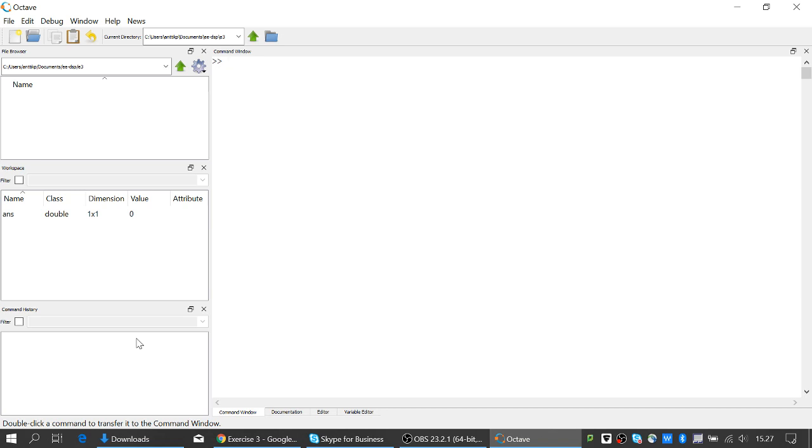So a stable system. And based on the theory I showed you earlier, the amplitude response should look more or less like, well, here we have Fs/2. We have the amplitude response going to 0 here, and we have a local maximum here. Maybe it looks something like that. I don't know. We will take a look. We will see it in a few minutes.